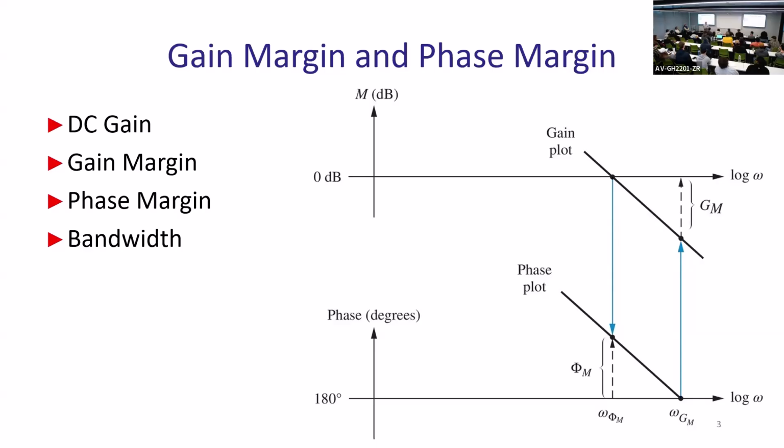Typically what people do, they have some sort of proxy for bandwidth, like how wide that looks after it falls. So they look from the right side to the left side, and they go, when I'm getting to the peak here, I'm taking 3 dB from the peak, and this is where that band is. So going kind of backwards instead of going that direction and lowering by 3 dB. So it's 3 dB from the peak, and you have other definitions for that as well. There is no unique definition for that type of system. So be careful even to define what it means, because the textbook defines it very vaguely. It says from flat, but sometimes you don't have a flat part.